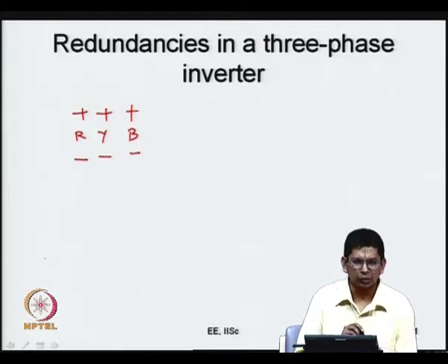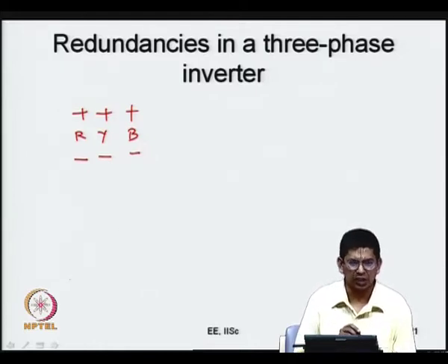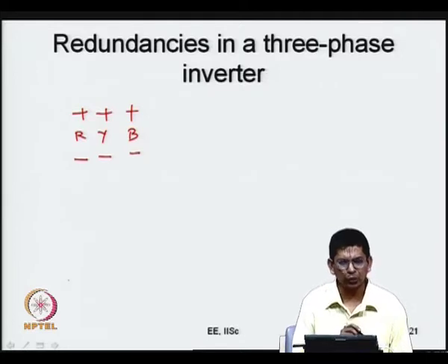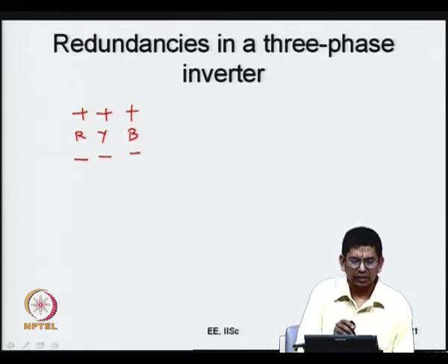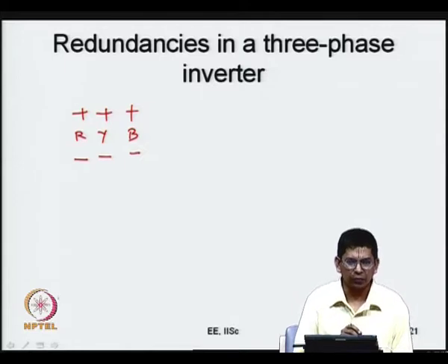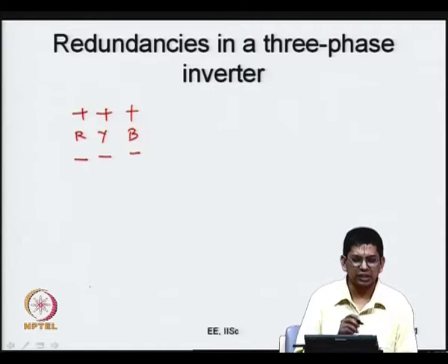So, the normal thing to do is use both the states, that would be the conventional wisdom, and also you do it equally, and that is what you do in conventional space vector PWM, which we will discuss a few classes later now. So, you will see that there is a redundancy. The same way as with the 0 applied, there were 2 different states possible for you. Here also 2 different states are possible now. All the poles can be connected to the top throw, all the poles can be connected to the bottom throw. That is how it turns out to be now. So, that is a redundancy now.